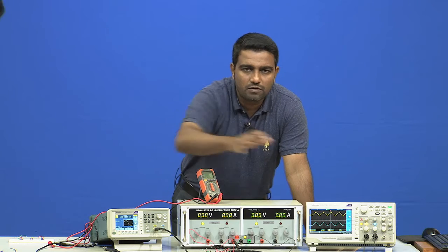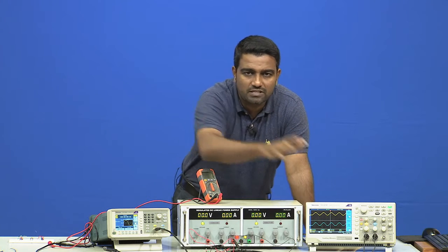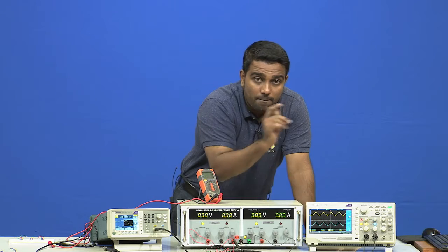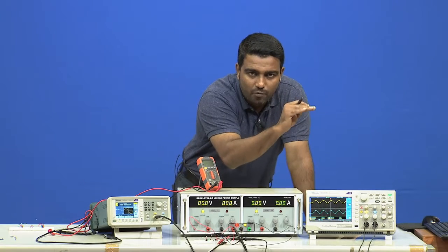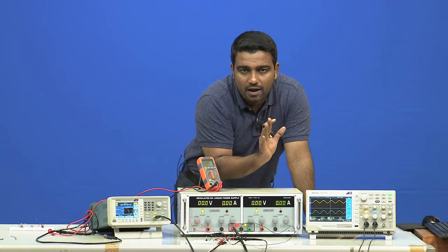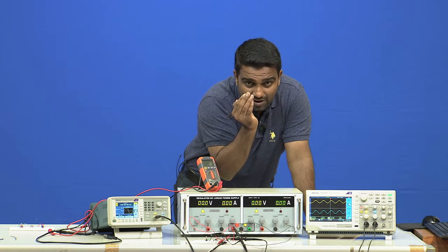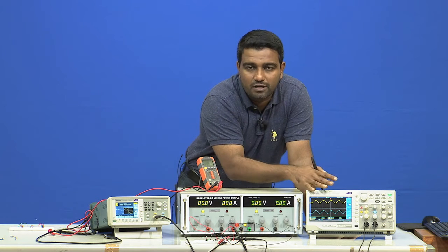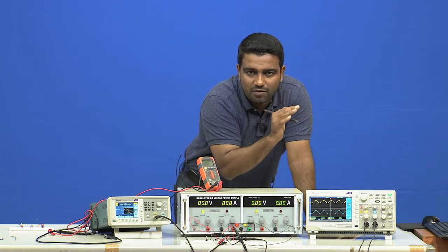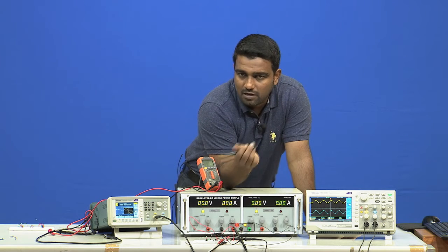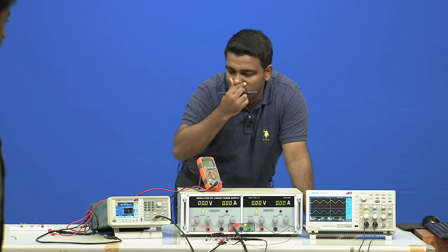We see input, we see output, we increase the input, we see a change in output, we keep on increasing the input, we keep on seeing the output increase, but that output will clip at one point which is more than the bias voltage, or it will clip a little bit less than what the bias voltage is, that is 15 volts. It will clip somewhere around 13.5 or 13.6, we will see, alright. So, let us apply 0.5 volts first.